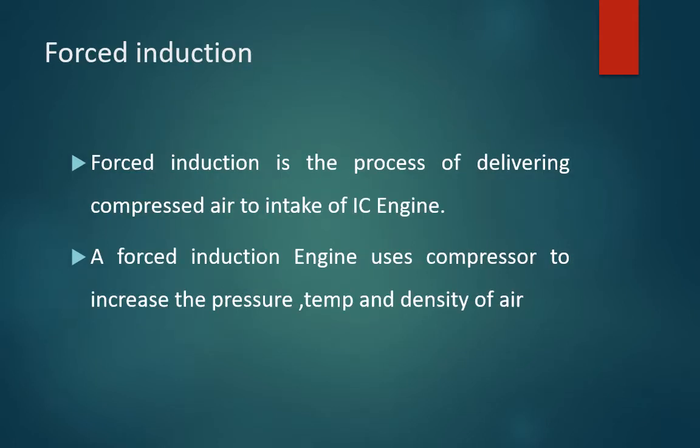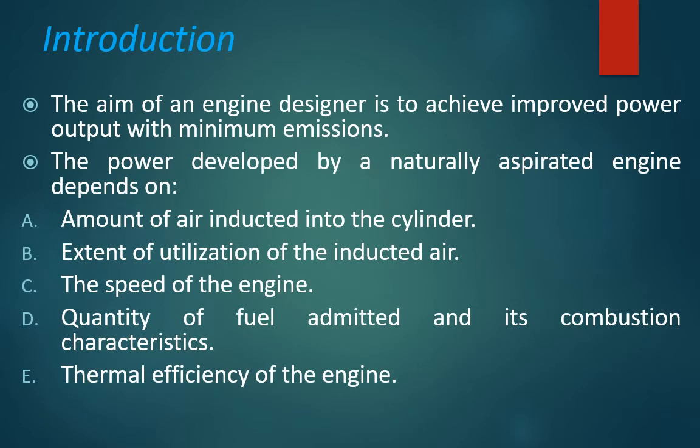When we talk about forced induction, it is a process of delivering compressed air into the intake of the IC engine. A forced induction engine uses a compressor to increase the pressure, temperature and density of the air. Before letting the air into the cylinder, the air is compressed, the pressure is increased, and the density of the air also increases obviously when the pressure is increased. That air is forced into the engine. That category of induction is called forced induction. So we will talk about the supercharger and turbocharger.